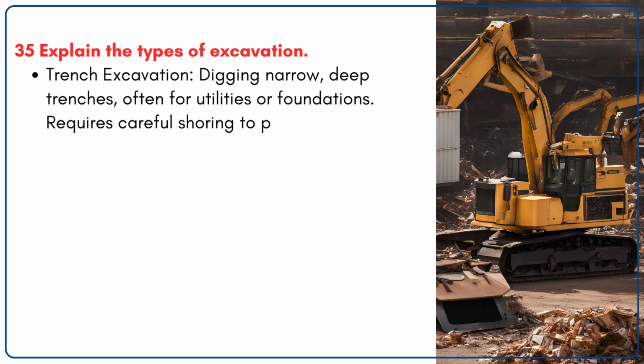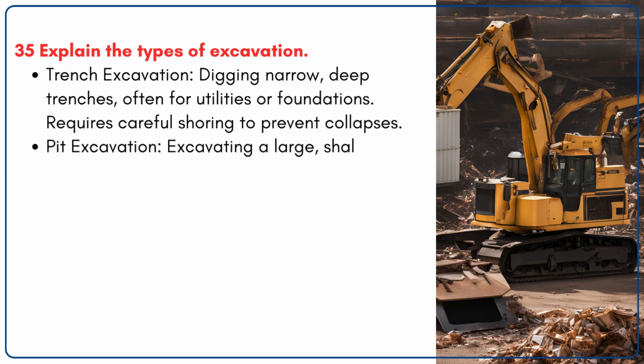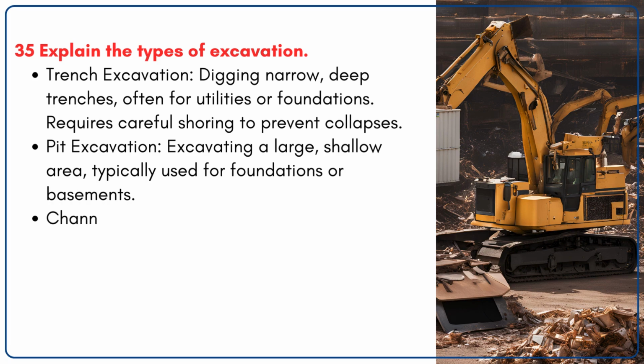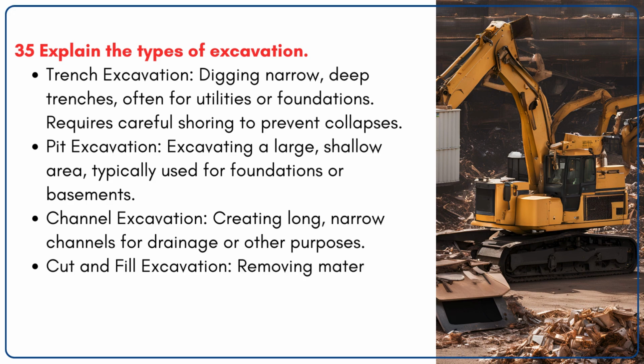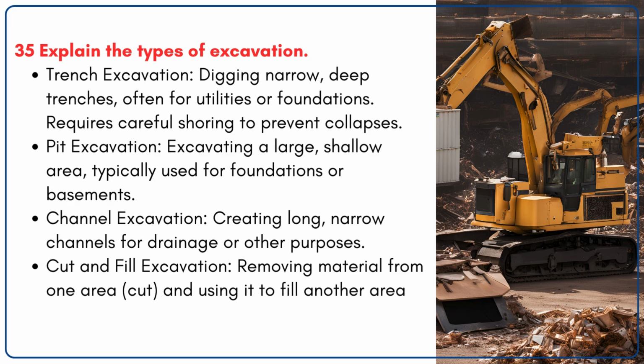Requires careful shoring to prevent collapses. Pit excavation, excavating a large, shallow area, typically used for foundations or basements. Channel excavation, creating long, narrow channels for drainage or other purposes. Cut and fill excavation, removing material from one area, cut, and using it to fill another area to create level ground.